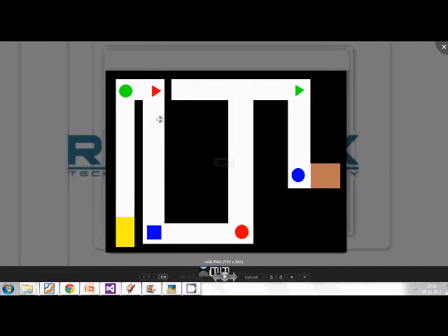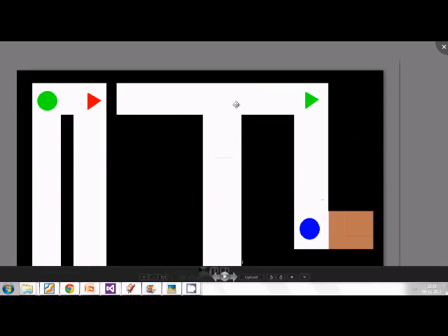Having done my blob detection, I have all of my separate blobs, or the colored patches, and then I find out which two are connected to each other. Okay, this is connected to this, which is connected to this. Suppose I can find that out. Then I'll have some idea of the sequence of symbols, and how that sequence is laid out in the actual arena. Now I'll come up against a problem when I get to this T junction.